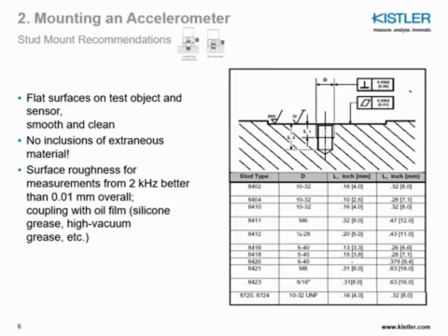Most of the studs are aluminum anodized. They are adding a little mechanical filtering, a little bit of mass maybe, but not that much. So you will see later that they have low influence on the frequency response. Whenever stud mounting the sensor, the coupling surface must be as smooth, flat, and clean as possible.